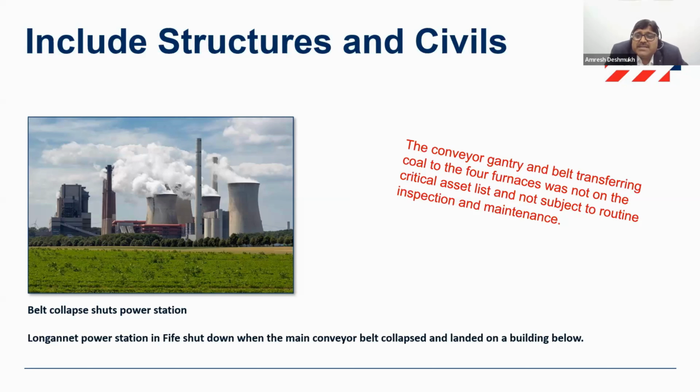Now remember, this is very important because you do not do structural audits every year. You do it at a frequency of 3 years or 5 years, and based on the certification that the structural engineer does, you're going to use it for 3 years. Even if you come across scenarios where you identify some failures, you won't be calling the structural engineer immediately to address that issue. You'll generally do it when it comes up on the predefined cycle of verifying the structural stability.